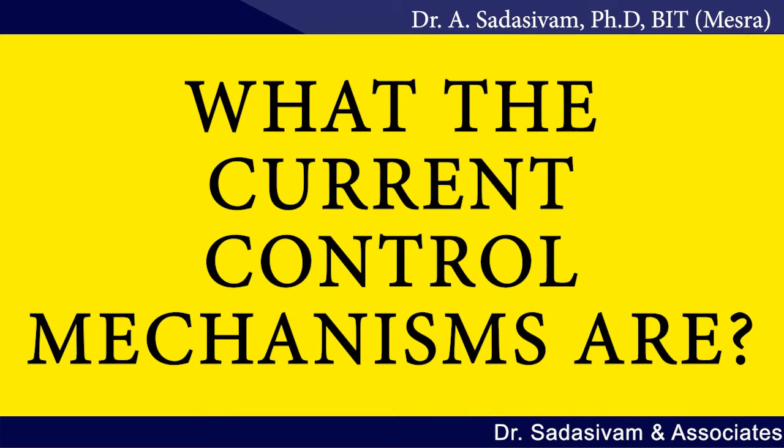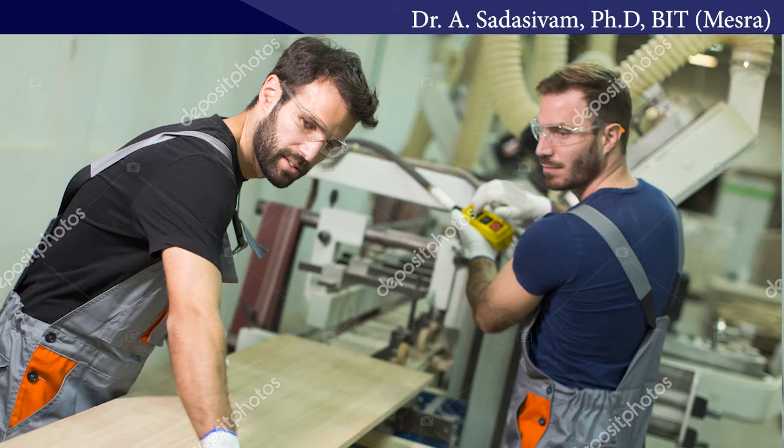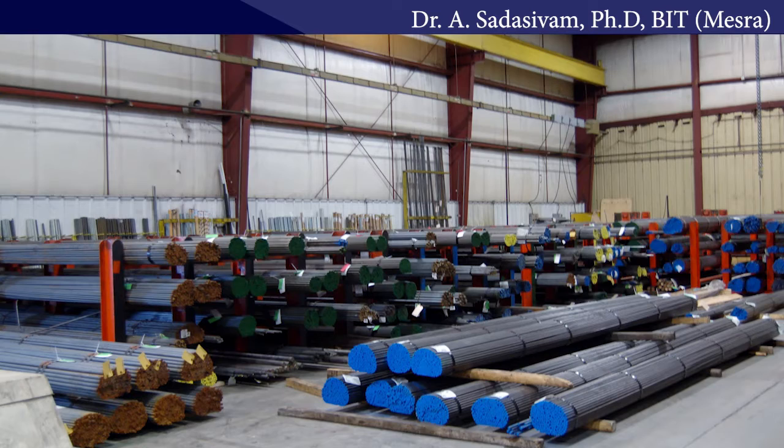And then we will talk about what our current control mechanisms are. For example, if there is a failure mode, there is a potential cause of that. The potential causes could be anything. Your man could be a reason, your machine could be a reason, material could be a reason, your method could be a reason, right? Potential causes we will identify. We will also talk about what is the current control on that, and then we will investigate in terms of how we can make certain improvements.